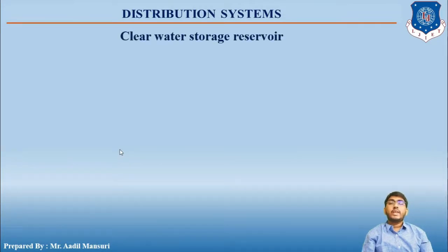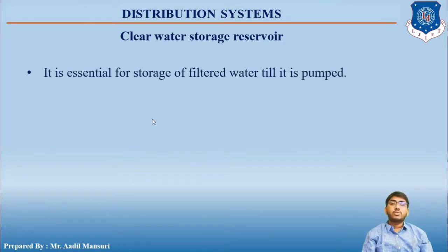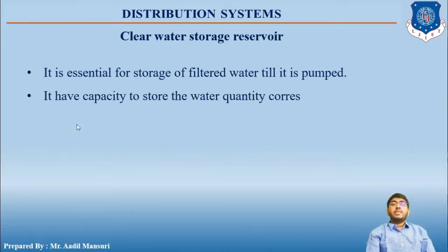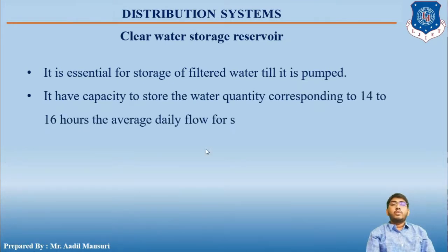Let us have a look at the next topic, that is the clear water storage reservoir. It is essential for storage of filtered water till it is pumped. We all know that once the water is treated in the treatment plant, it has to be supplied, but before supply we need to store. Next, it has the capacity to store the water quantity corresponding to 14 to 16 hours of the average daily flow for storage.